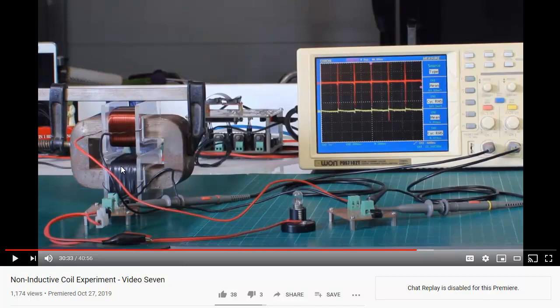Okay, so just to reiterate, if you haven't seen this video, the input coil here had a 10% duty cycle. What you see on these spikes here is the input. Everything else that appears flat is when the input coil is off, so there's no way for current to flow on the input coil from the input power source, because the MOSFET's off.